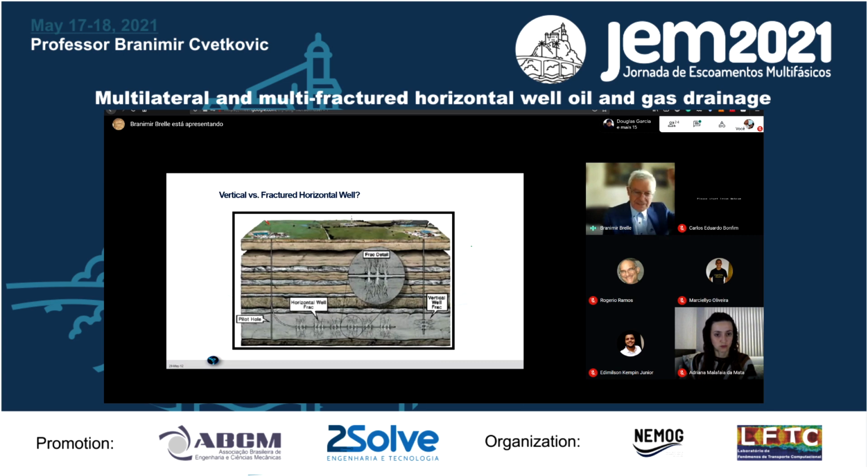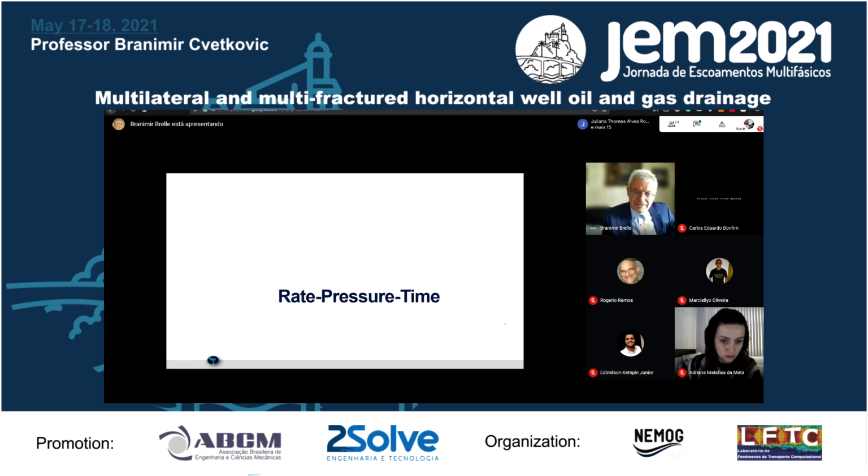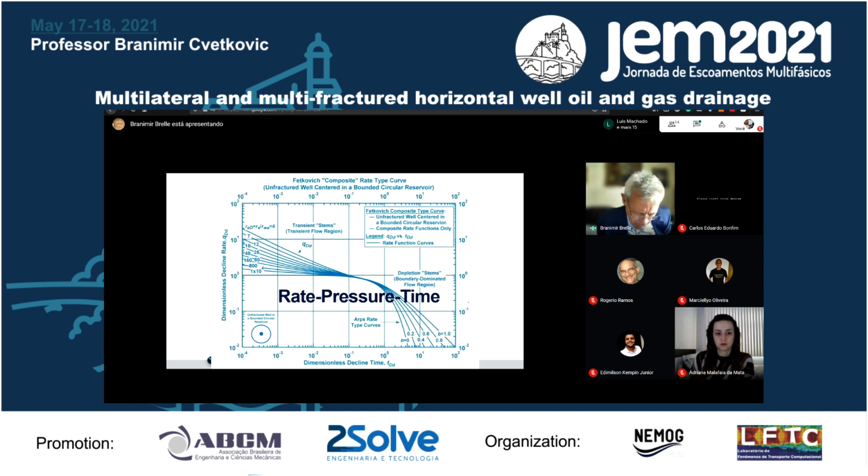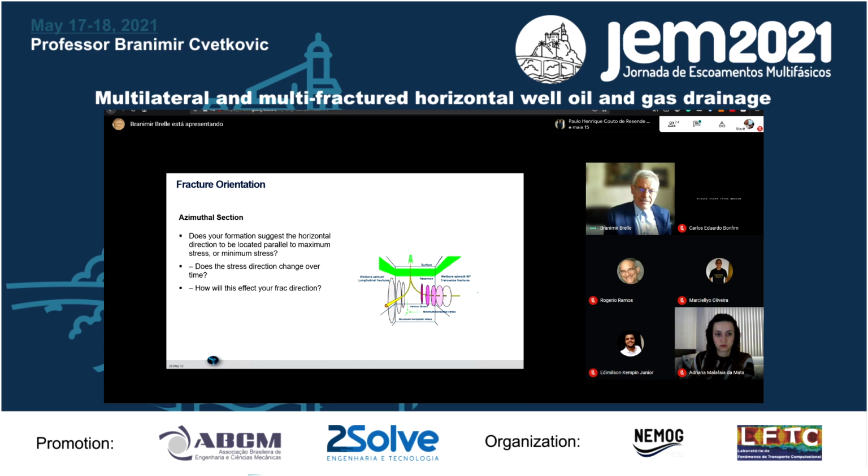So here is how this fracturing looks like. Now I have a model. The basic of the model was provided. I have here a vertical fracture well. In my run, I have also this, but also I have this fractured. These are the stages: 1, 2, 3, 4, 5, 6 stages. So I like to name it as a rate pressure time analysis because we usually talk about rate equals 0 when it's pressure time analysis, what we name as a well testing. Here is the practically in short.